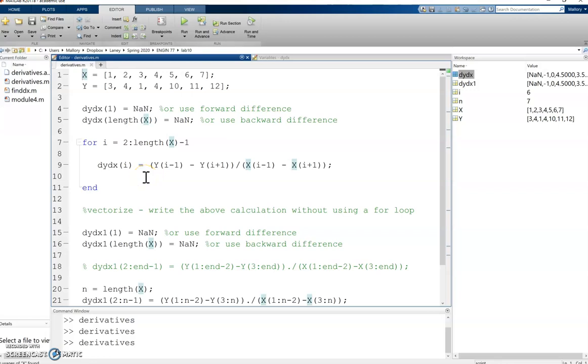In this video, I wanted to go over a useful tool in MATLAB, and that is called find and replace. So let's say I have used this capital X throughout my code and I don't want to use capital X anymore. Or I only want to use capital X for some of these, and some of them actually should be lowercase x. So I can use find and replace to find everywhere that I've used them and replace them. And I can either replace them all at once, or I can go through piece by piece and decide which ones I want to replace.